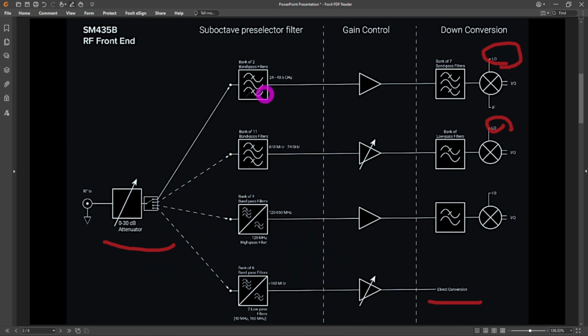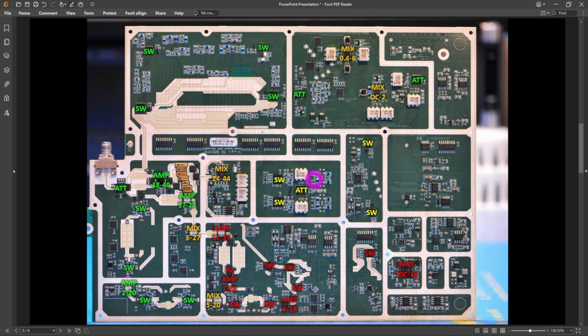Now, you have to keep in mind that this is a unique architecture in a sense because there is no YIG selector here. With a YIG, you're going to have a very different architecture, but then you wouldn't be able to do the streaming of 160 megahertz, and the YIG needs to be taken out, and it basically ends up being in a similar architecture at the end of the day if you want to have the real-time capability. So this is not to be mistaken with a traditional spectrum analyzer, for example, that just looks at a very narrow frequency range. This is a totally different story and very difficult to do, of course.